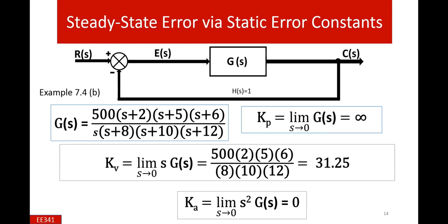So our discussion is still toward understanding the concepts of stability with different types of input and different system types all together, and definitely it will be helpful to design a controller for stable systems and to know what type of input will be suitable for that type of system. So -8, -10 and -12 are the positions of the other poles.